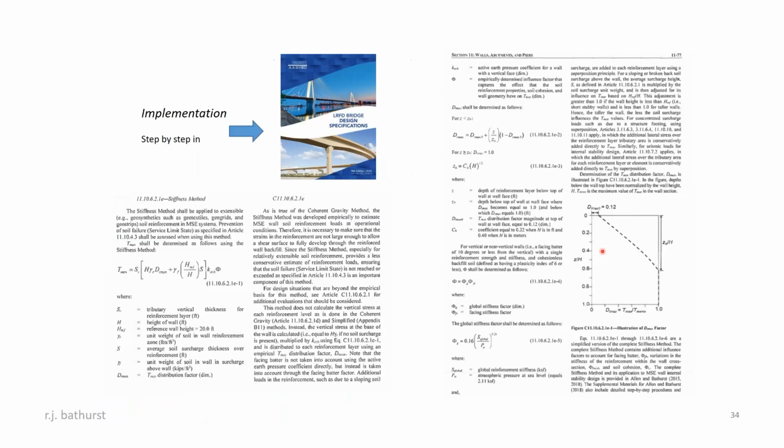The implementation of this method is a step-by-step procedure. And if you go to the LRFD code in the US, you can find all of these equations that I've spoken about, and you can walk through these equations for any trial design that you're interested in. The equations are quite simple. They're amenable to putting into a spreadsheet. And when we were developing the method, that's what we did. Just spreadsheeted these equations.